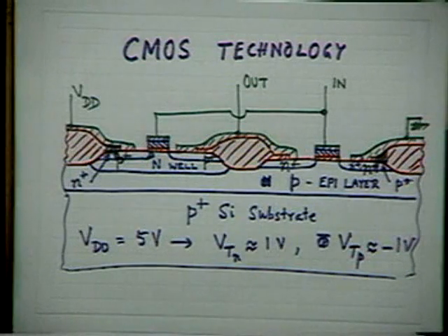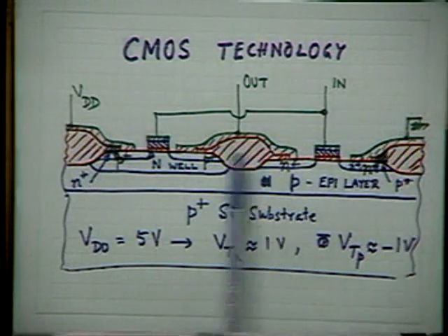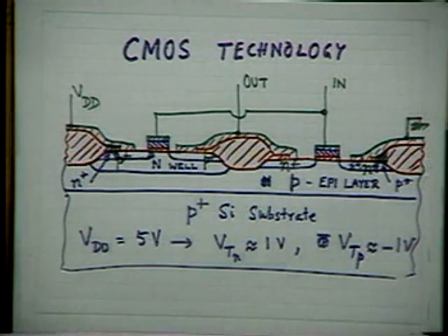So you understand that CMOS technology is much more complicated than the normal NMOS technology, because we have both types of devices, both NMOS and PMOS, and normally both are enhancement mode. That is the requirement. Please remember, in CMOS technology, this is the driver transistor and this is the load transistor. Both transistors are enhancement mode devices till today.